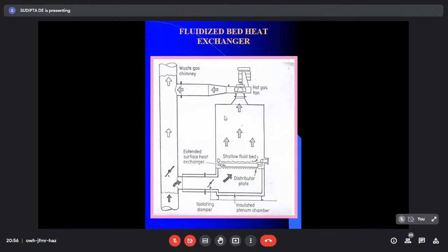On the heat transfer surface, you will have continuously solid particles impinging on the surface. And if the solid particles are heated and have a high temperature, then effectively the heat transfer between this air-solid mixture and the surface will be several times increased compared to the normal gas to surface heat exchange process. That means the fluidized bed heat exchange process is several times larger than the air to surface heat exchange process. I'll show the graph later on.